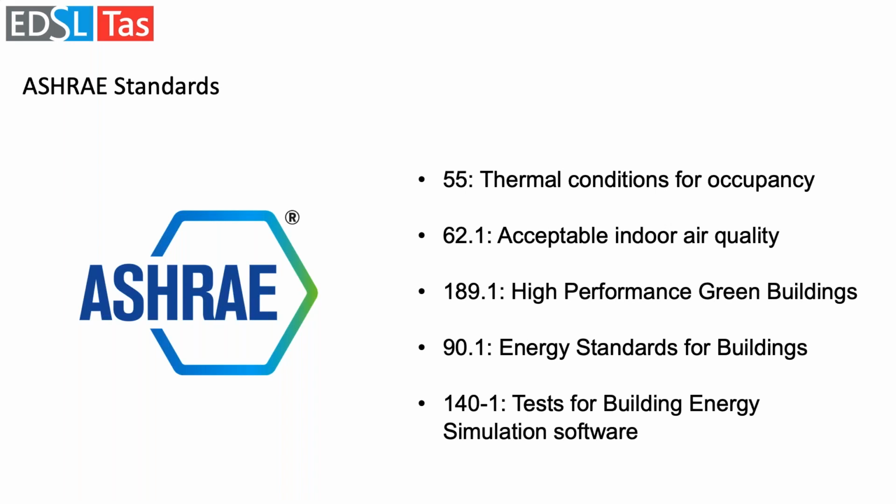So ASHRAE 55, thermal conditions for occupancy; 62.1, setting acceptable indoor air quality and the amount of ventilation that's required for that. One that we like particularly, 189.1, criteria for high performance green buildings. 90.1, which we'll be touching on a little bit later, are energy standards for buildings. Actually, 90.1 has been adopted into some LEED requirements, which we'll touch on later. And then probably the one that is nearest and dearest to our heart on a day-to-day basis is 140-1, which tests the validity of the results from building energy simulation software.